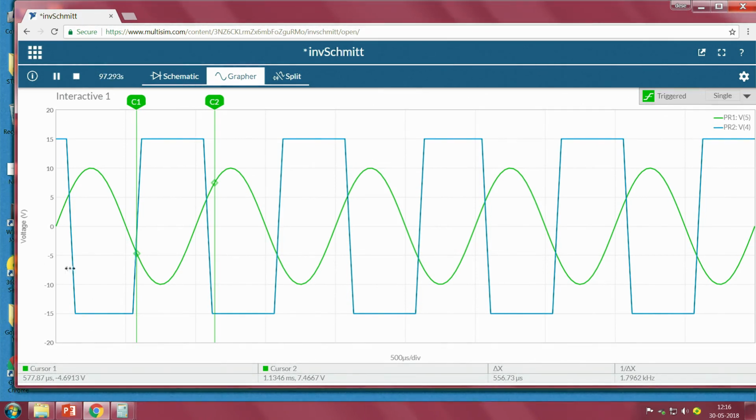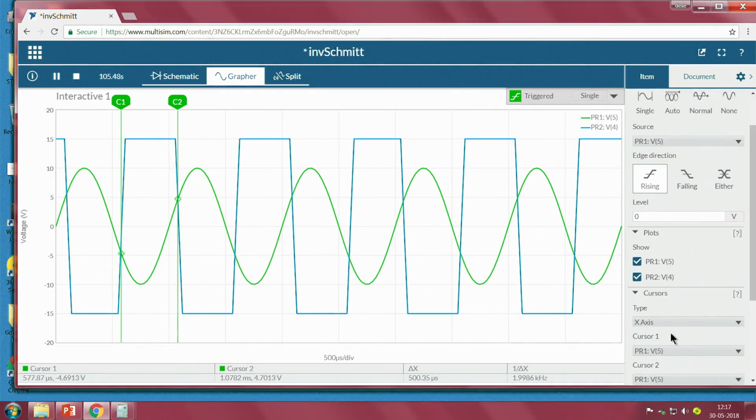I can see when the input goes lower than this particular threshold value, the output goes towards plus 15 volts. Similarly, when I move towards the positive higher threshold, somewhere here, you can observe the cursor at 4.3032. So, I have to increase it a little, somewhere around 4.7 approximately. I can see that when the input is higher than that higher threshold value, the output is minus VCC.